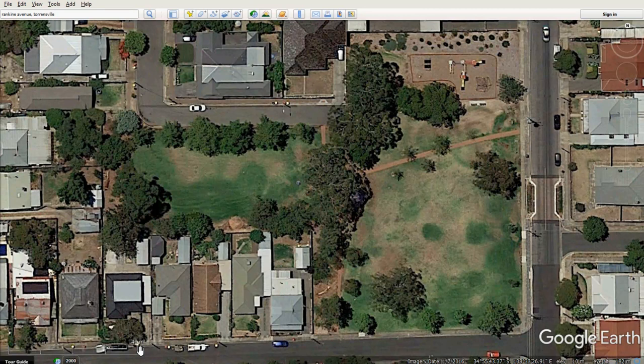There are two issues that are important when you're in Google Earth. The first is to make sure, and I hope you can see it, down at the bottom of the screen, I've made sure that my scale is showing. And the other issue is I want a top view, a precise plan view, and the easiest and quickest way to do that is to hold the wheel of your mouse down and just pan up, and that will give you a precise top view. You might prefer to do that first and then adjust the magnification a little. Just make sure that the bar is showing.